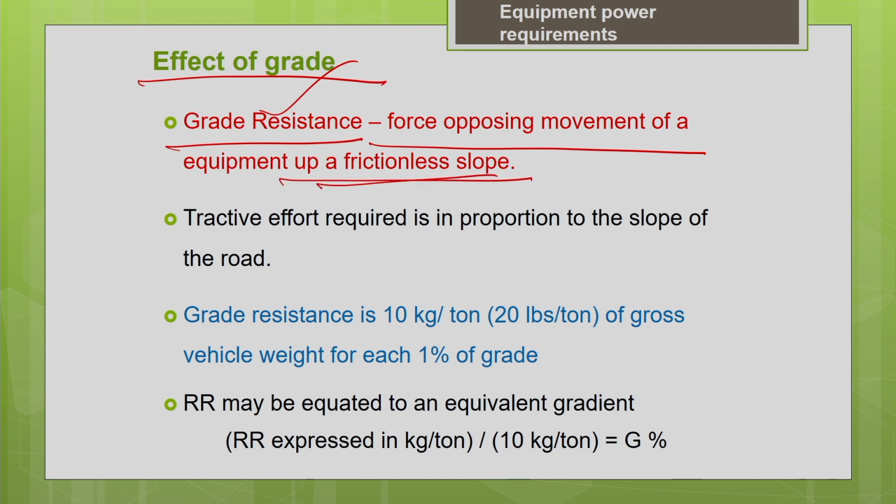So, here we are going to consider the effect of grade, grade resistance alone. How much tractive effort do we need to overcome this grade resistance? That depends upon the percentage of the slope. How steep is your slope? According to that, the tractive effort requirement will vary. Similar to this, you should also know about grade assistance.